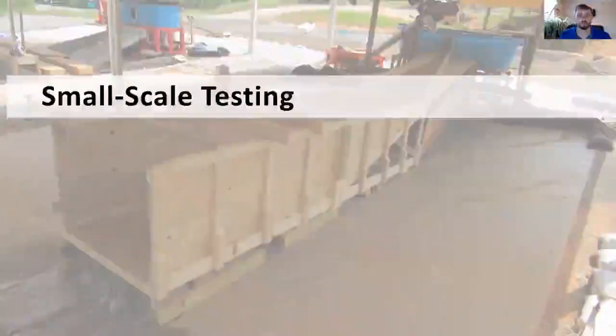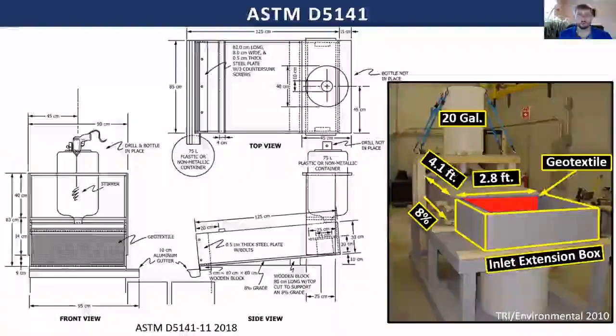So we'll start with the small scale testing. What I'm showing here is the actual ASTM D5141 design specs that is provided, as well as an image that has been constructed. Essentially, a 20-gallon container will be filled with water and sediment based off the specifications. It'll be mixed up, and then that is introduced into roughly a 4-foot long by 3-foot wide box where at the end of it a geotextile is attached. And this is the current standard for testing geotextiles.